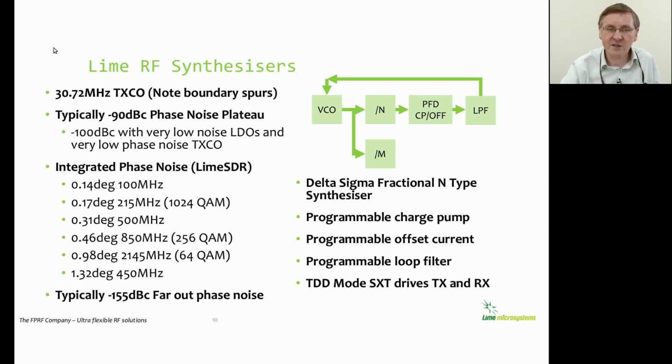The synthesizers used in the Lime transceiver are a classic PLL type synthesizer featuring a voltage controlled oscillator, a feedback divider, a phase frequency detector with a charge pump and a loop filter, and a feed-forward divider.